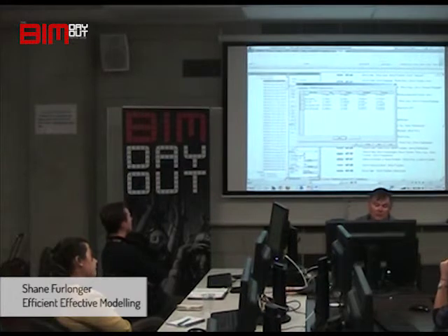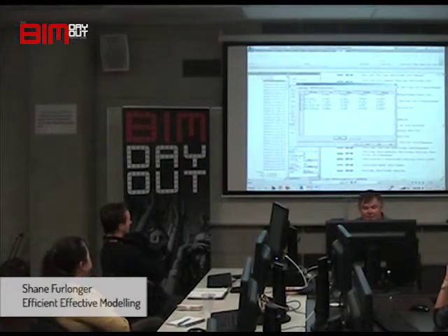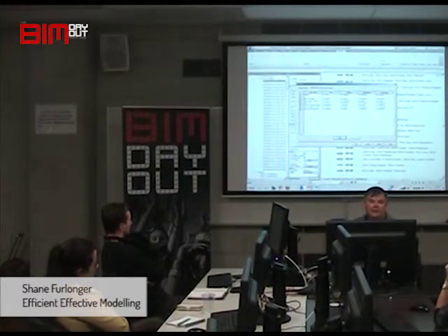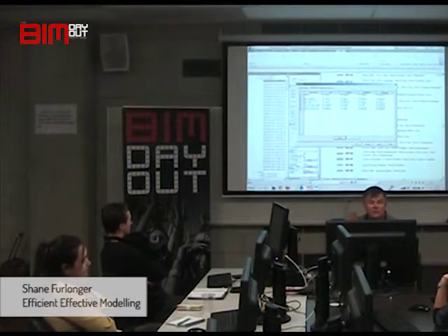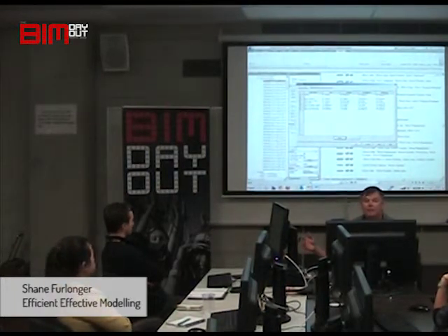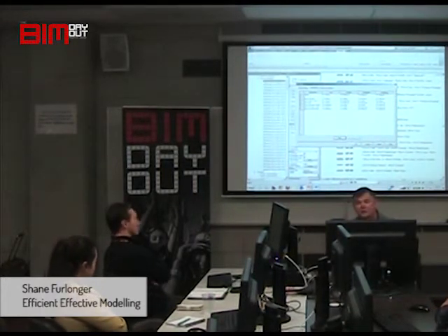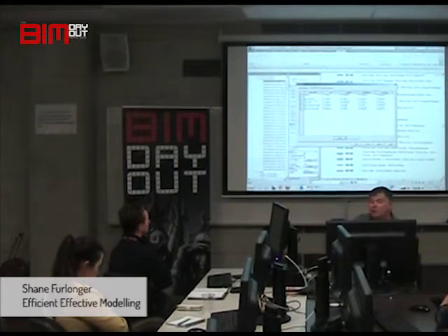Temporary is very simple, at least. That's created and demolished in the same phase. So that's easy to remember. And it doesn't matter what phase that is. You can call your phases, like I said, 1 to 10. Doesn't matter what phase it's in. It only exists in the phase and it's demolished in the phase that it was created. And it's shown in a specific way.